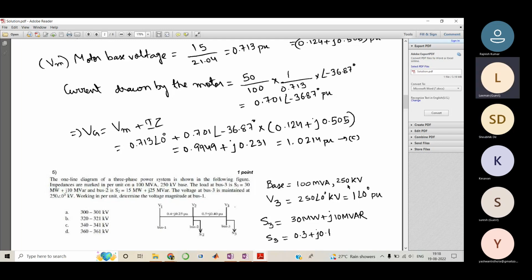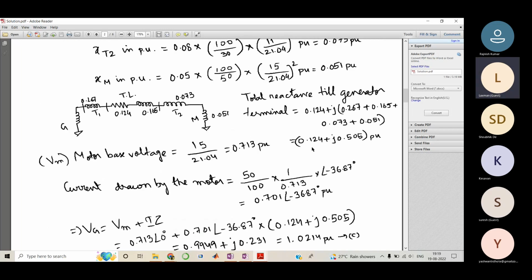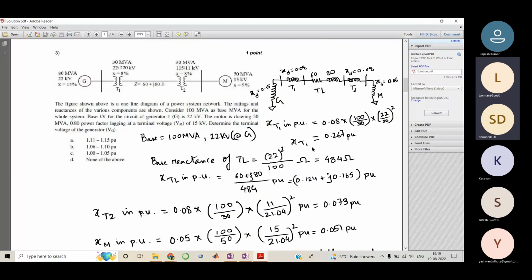Is it not required to convert that 50 MVA to a per phase value? No, it is not required, because both are the same. The base value is being calculated in per unit, so it is not required. Even if you do it in per phase, the root 3 will get cancelled at some point. But 100 MVA, we are defining it for the phase value, right? Or is it a line rating? No, while you are using per unit, you don't have to consider phase or line values.